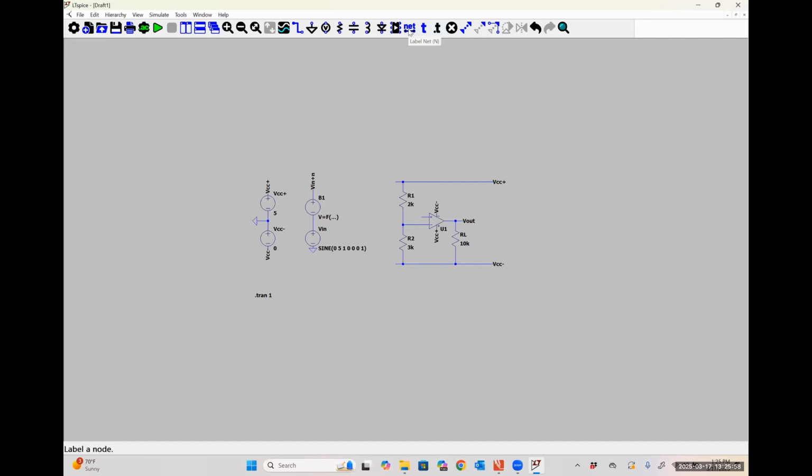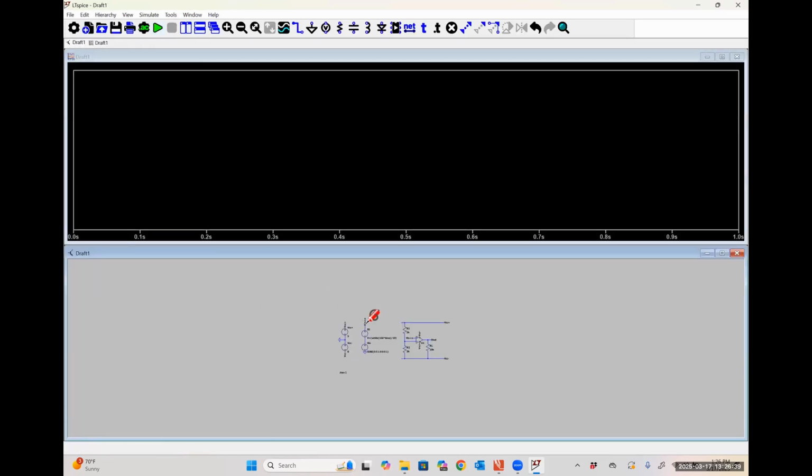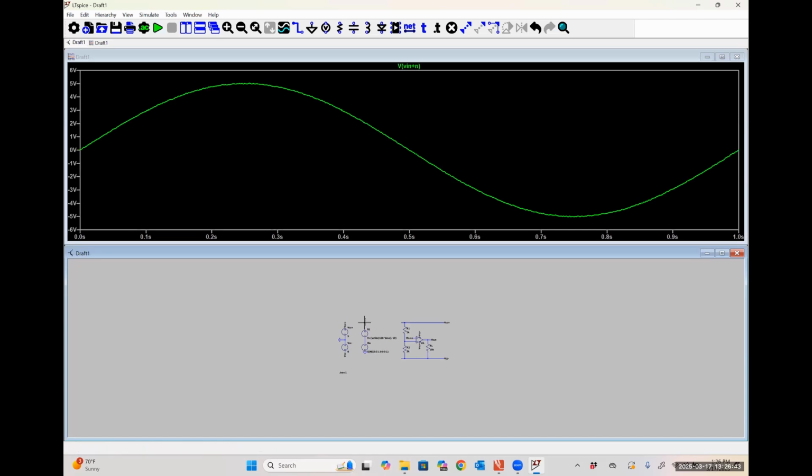Delete that guy. And now I'm just going to edit this one. I'm going to say that the voltage being provided by this extra source is going to be white noise. You can change different parameters for white noise. You guys don't literally ever have to do this. I'm just trying to show you something interesting. So I'm going to have a white noise voltage generator added onto my simple input sinusoid. I'm going to run my simulation. And if I click on this Vn plus noise, you can see that it's not a pure sinusoid anymore. There's a little bit of noise added on top.